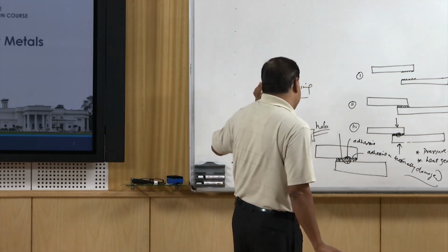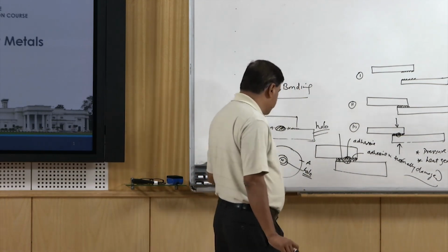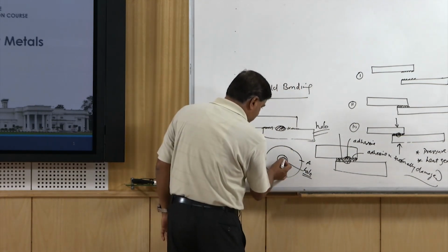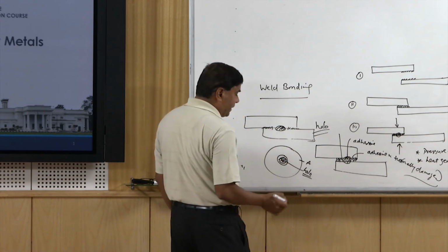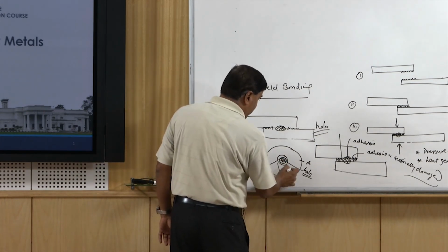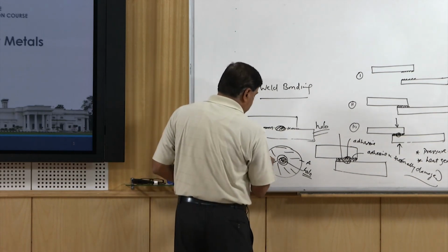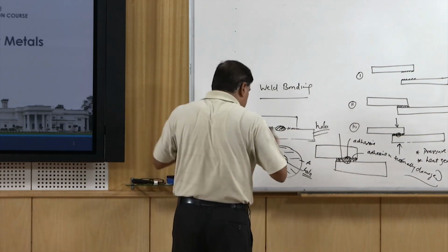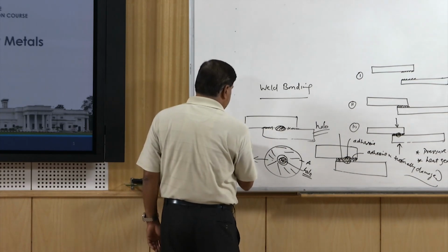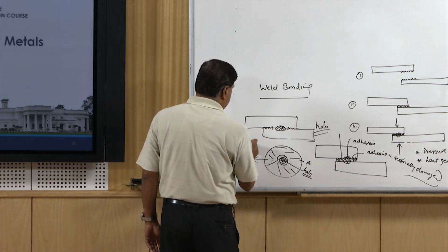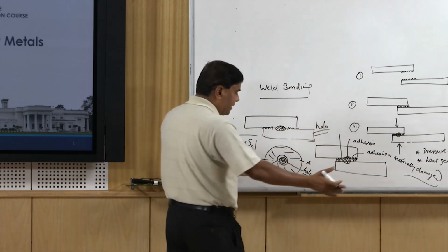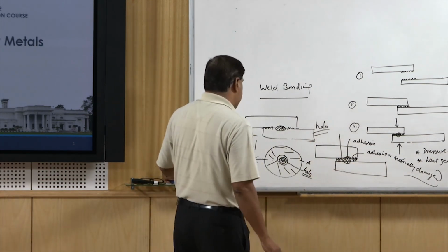As far as the factors contributing towards the strength, the nugget provides the metallic connection, and the adhesive all around it provides the adhesive strength. So the total strength of the joint will be the sum of the strength due to the adhesive plus the strength due to the nugget. The sum of these two will determine the strength of the weld bond as a whole.